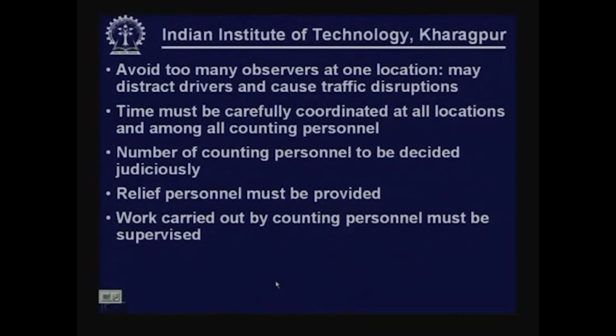Avoid too many observers at one location, as they may distract drivers and cause traffic disruption. We want to record the natural condition, what is happening naturally. So, if too many people are making a crowd in one place, the drivers may think, what is happening here? Their natural movement may get disturbed, and we do not want that. So, that is to be avoided.